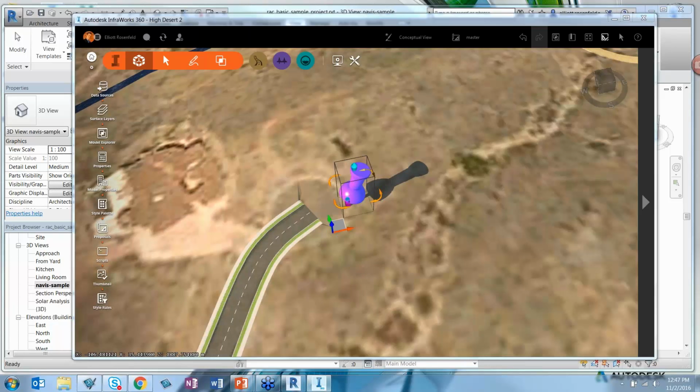But as you can see, you've got some manual processing to do here with FBX and IFC. With IFC, I'm pretty sure you won't be happy with the colors. It's a quick process, but it doesn't bring out all the textures and everything. It's a very muted file. So if you don't need a super high-res nice model in your Infoworks, IFC is the quickest. But you still need to go through this process.